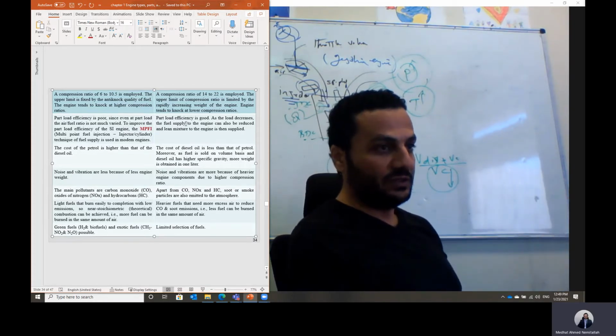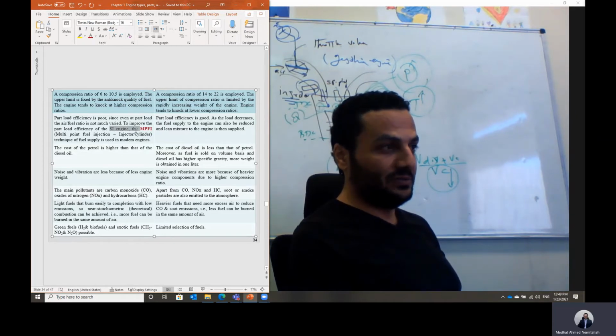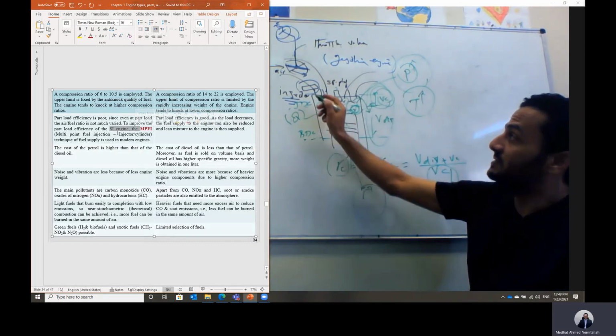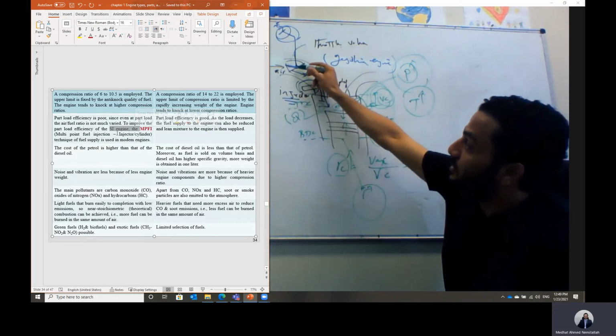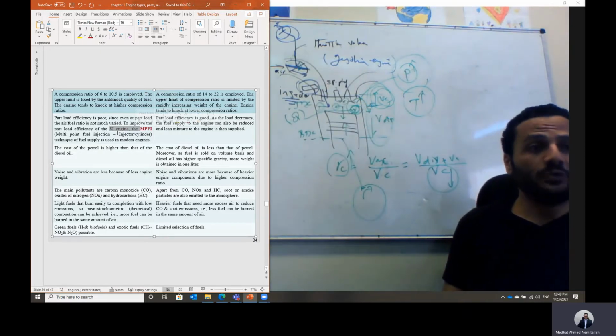So it is much more efficient in fuel economy in this case. But that, ya shabab, was in the early version of the spark ignition engine in cars, specifically in the case of cars. In the old version, they used to have this injector fixed to the throttle valve. We call it single point injection.